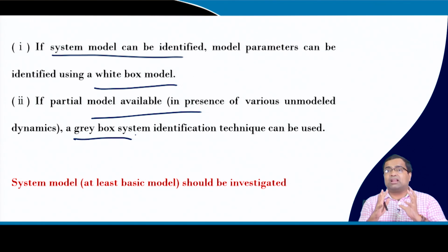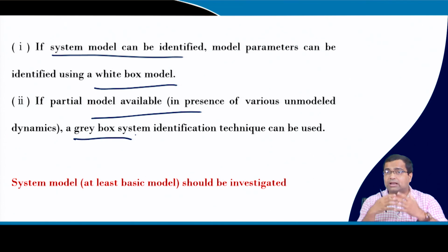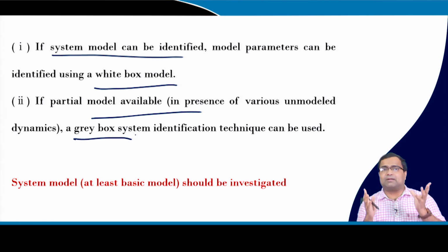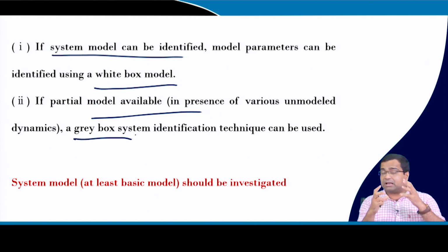And such model identifications are very important for future power converters, where we are talking about digital twins, where there can be automated tools. From the runtime of the system, because there are a lot of online controller tuning methods, there are very highly cited papers available, where tuning using a digital platform can be carried out by simply identifying the model in real time or measuring some phase margin, as well as some parameter in real time, and you can tune the controller, okay.